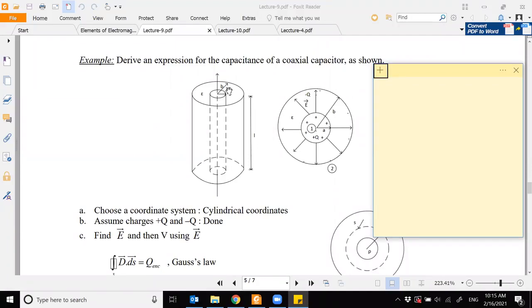It forms a sort of filter because it's an RC. So it forms a sort of filter, and therefore that capacitance and the resistance value will decide what is the maximum frequency your coaxial cable can take. That means your coaxial cable can pass that signal through.